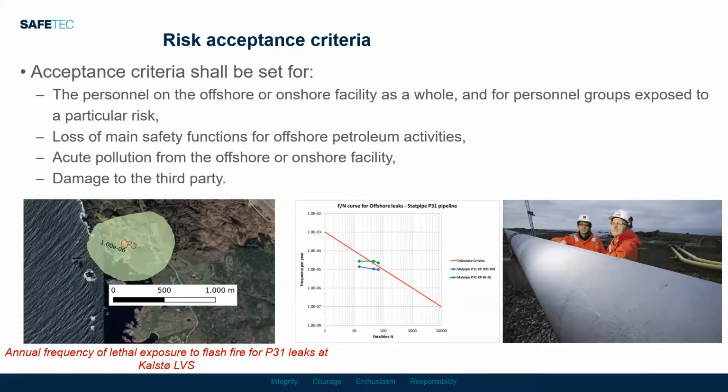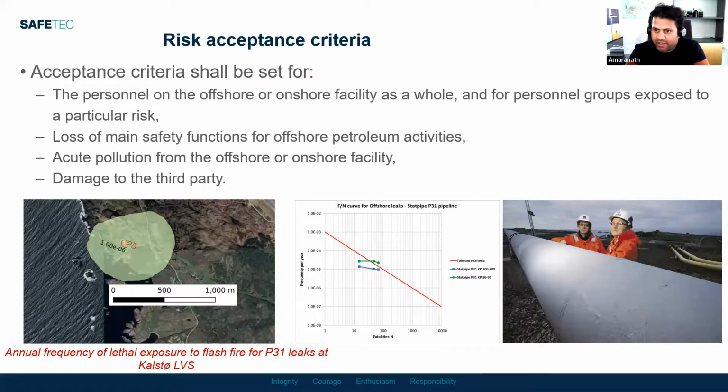If you just lay the pipeline on the seabed, there is a possibility of damage due to anchors, so we need to basically bury the pipelines. What is the minimum? Is there any standard depth for that? No. For offshore pipelines, there's a huge risk of damage due to trawling and anchoring.